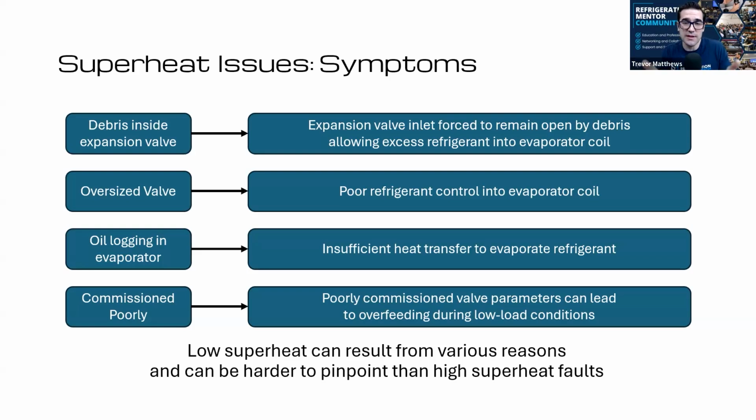Now with the trend graphs and these controllers, and really any manufacturer now with case controllers, they're doing a great job with the logging features. As long as it's set up and you have the temperature probes, it helps me so much. And then showing these technicians in these CO2 programs, they're like, I never thought of that, because I'm not used to seeing how a TX valve reacts and what percentage the TX valve is open. We only have a few set points mechanically to check.